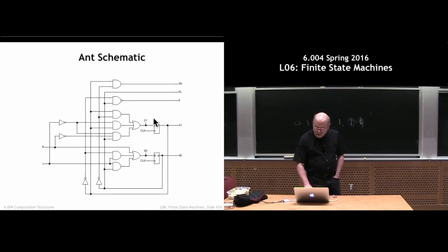And in fact, here's my 2 state bits, and here's my combinational logic cloud that's computing both the next state and the output values. So this is the entire schematic of a robotic brain, of a robotic ant. We're going to make a fortune next Christmas. Okay, so all the behaviors that you see all these things doing really can be captured using this sort of design methodology. Any sort of sequential logic, we can use this design methodology.